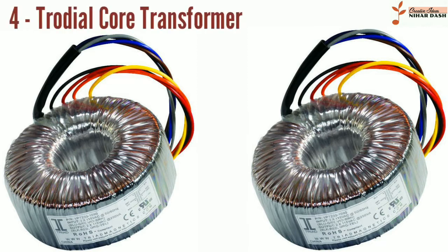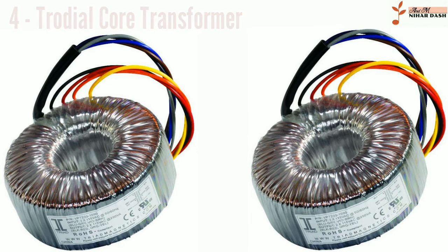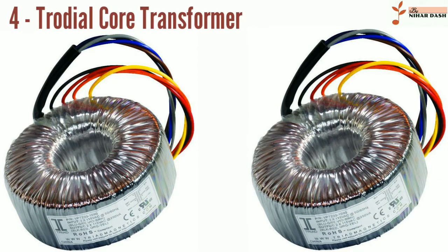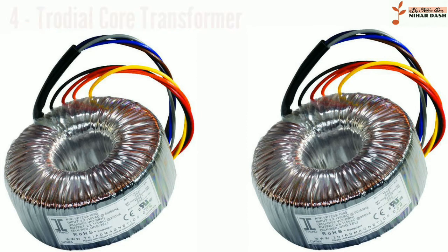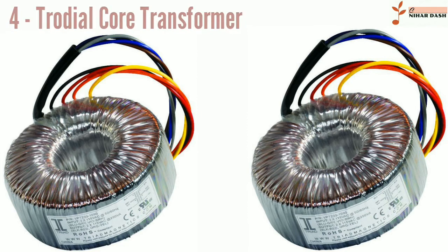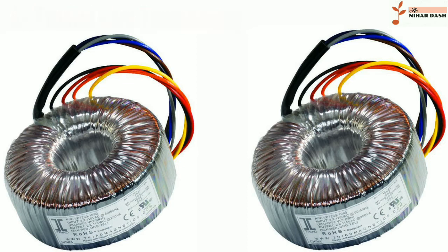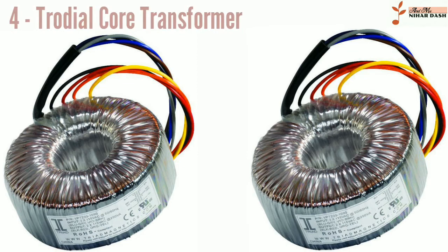Toroidal cores. Small toroidal core transformer. Toroidal transformers are built around a ring-shaped core, which, depending on operating frequency, is made from a long strip of silicon steel or permalloy wound into a coil, powdered iron, or ferrite. A strip construction ensures that the grain boundaries are optimally aligned, improving the transformer's efficiency by reducing the core's reluctance. The closed ring shape eliminates air gaps inherent in the construction of an EI core.